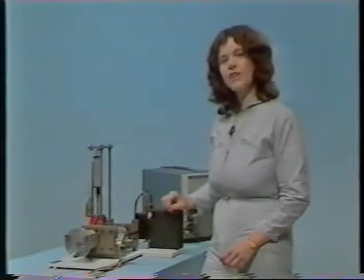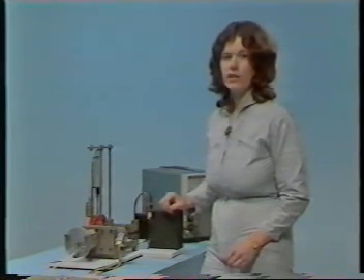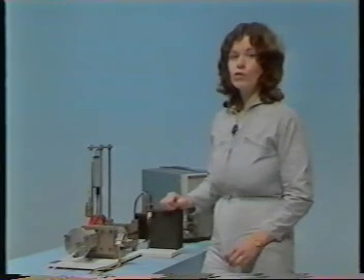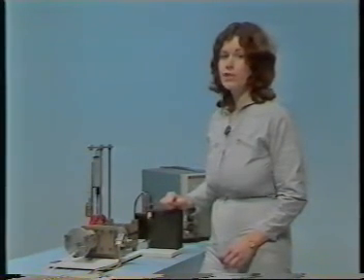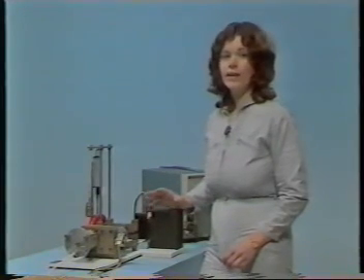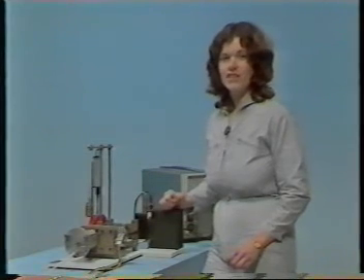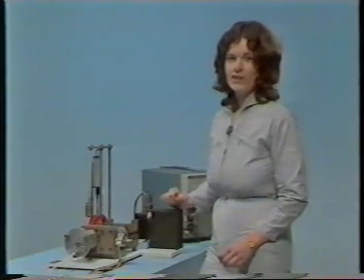The successful functioning of the regenerator is absolutely crucial to the success of the Stirling engine. In fact, there's a whole order of magnitude difference between the thermal efficiency of an engine operating on the Stirling cycle with a regenerator and without. Needless to say then, the development of effective regenerators has been exercising many fine minds over the last 20 years or so.